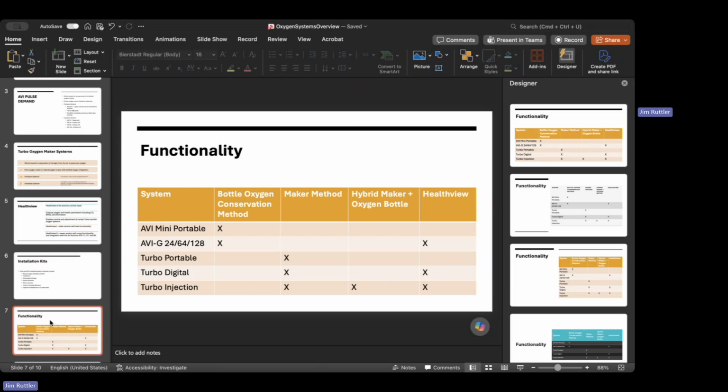And that turbo system, because it has a compressor pump, draws quite a bit more. For 12 to 14 volts, it's 6 amps, 80 watts. The turbos are limited right now, without a step-down converter, to 14-volt aircraft systems, but we are working on a 28-volt variety, which will be out in the next few months. That will save you some money if you want to wait for that and you have a 28-volt aircraft.